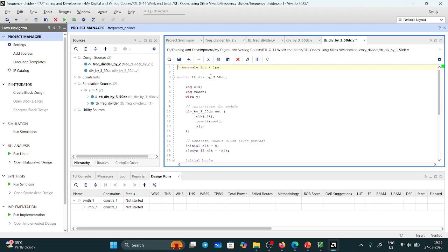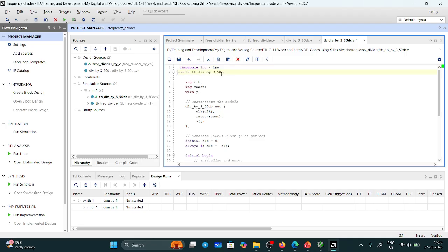So all modules don't operate at the same frequency. There will be some master clock, and inside that master clock there will be frequency divider circuits. Those circuits divide the frequency in such a way that, in order to synchronize, all the frequencies should be operated at 50% duty cycle. For the synchronization purpose, we are making that a 50% duty cycle.